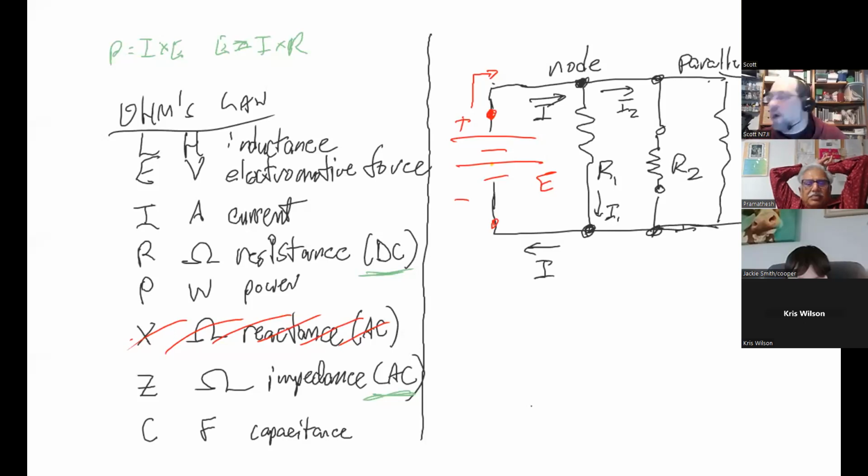This is how we wire our house. The reason we do this is because every device in the circuit experiences the exact same voltage from the power source, which means that even if this light, for instance R2, burns out, the other lights will still be lit. And again, this is called wiring in parallel.